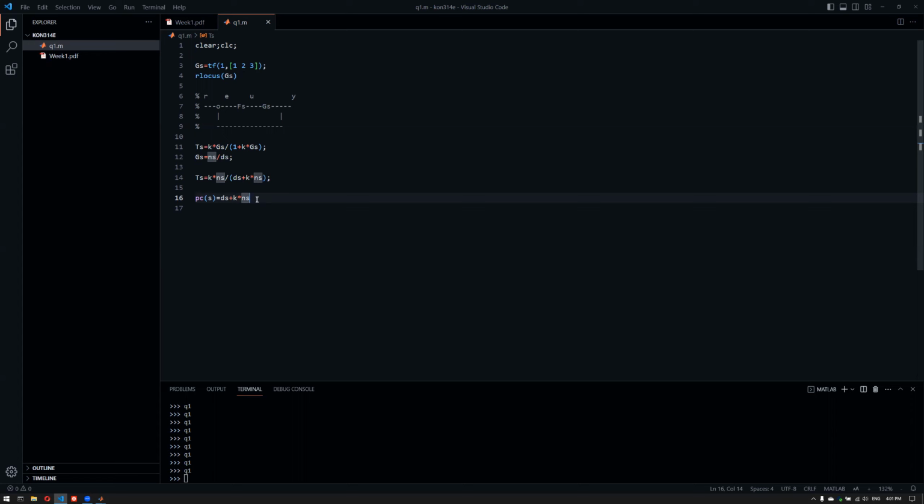And then we also need to come up with a certain K value that alters the system behavior in such a way that the desired specifications are met. For example, if overshoot should not happen, then that's one specification that we need to hit. And then there's the settling time requirement, and we're going to try to come up with a K value that meets all the desired requirements and also ends up in a stable closed loop system here.